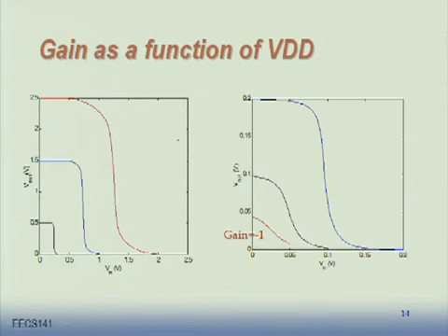I mean, this is a very robust structure. It's the exact same inverter that works well at 2.5 volts and 0.2 volts. And then eventually the gain gets worse. And when you drop it down to something like 50 millivolts, there is no more gain. No, it is in subthreshold. The whole thing operates in subthreshold.